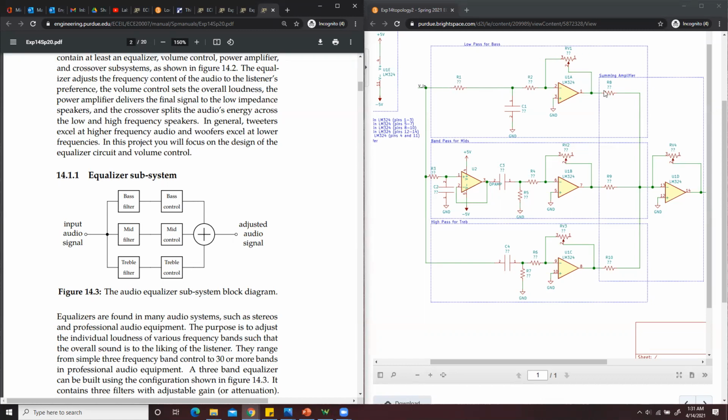filter and this amplifier together, these two circuits may affect each other because of the loading issue. For example, this R1 value is very similar to the value for R2. This will cause some loading issue. Okay, so there are two solutions to solve this problem. One way you can do is make sure the value for R2 is much greater than R1.